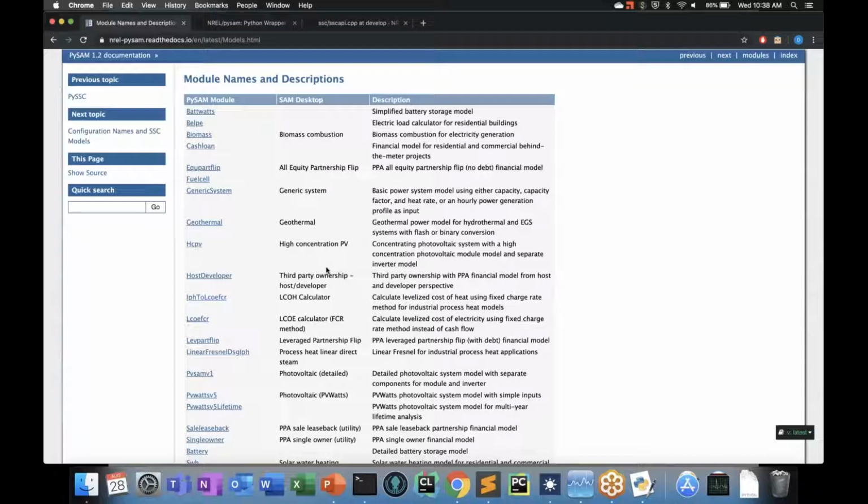We'll use the PVWatts single owner case example to go through the new features of PySAM. We will set up auto-completion in PyCharm, an IDE, access variables, and decipher error messages. To set up auto-completion in PyCharm, we'll start by creating a new project in the PySAM talk folder that I've prepared, and getting it set up with our newly created Anaconda environment. Not everyone uses PyCharm or an IDE, so this step is optional.